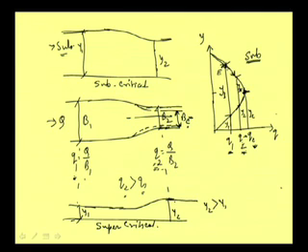Fine. Now, the point is that we can get critical depth by reducing it to a certain width, but if we reduce our width beyond that value, what will happen? Suppose we are reducing it further. Beyond BC, if we reduce, what will happen? For the BC value, bed width equal to BC, we are getting this YC.